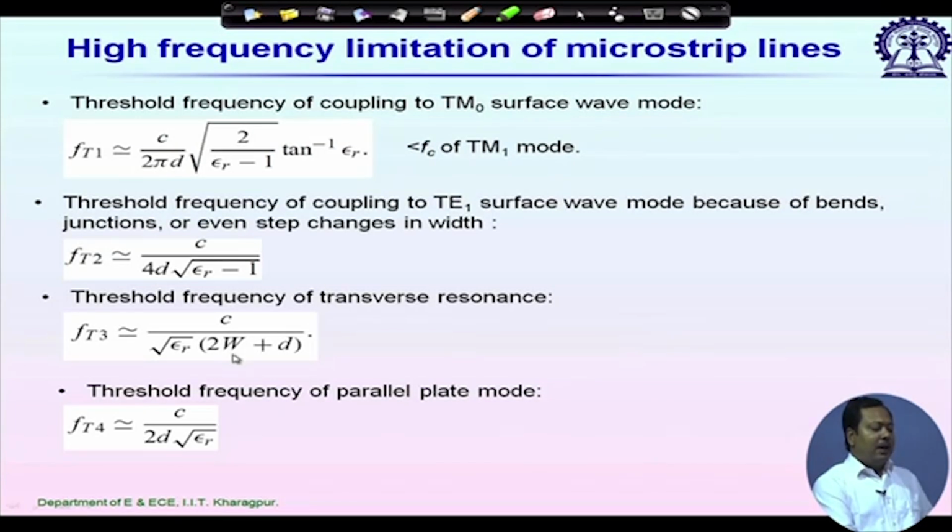And not only that, when we are designing millimeter wave components, we don't only deal with 50 ohm lines, sometimes we have to use a smaller impedance as small as, let's say, 35.35 ohm, or when we are designing filters, sometimes we also deal with much lower impedance, let's say 20 ohm.